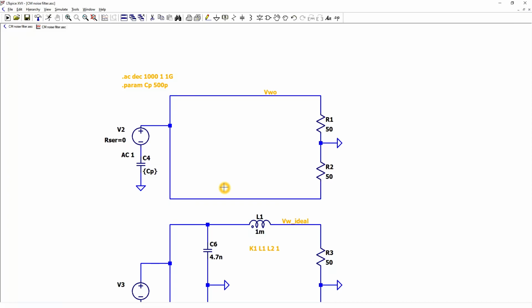This impedance will affect the performance of our filter, since the insertion loss of a given filter depends on the impedance of the source and the load. That is why using the insertion loss graph provided by the manufacturer to evaluate the performance of the filter in a product may not give realistic results. Also, one of these resistors will be the termination resistor and the other the impedance of the spectrum analyzer, depending on which line is being measured at a given time.